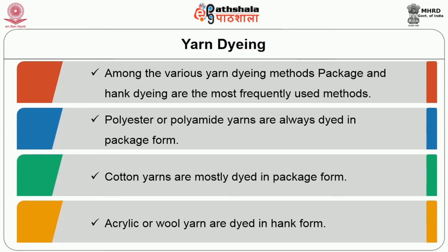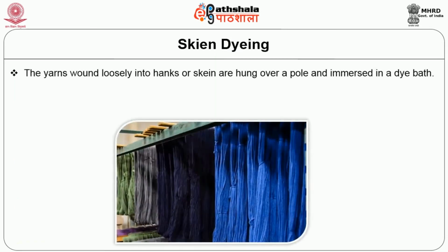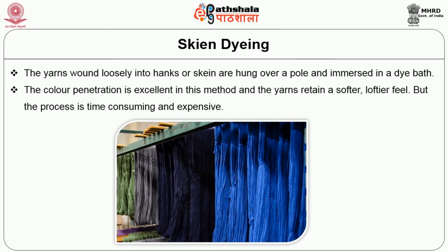Skein dyeing: the yarn is wound loosely into hanks or skeins, or hung over a pole, and immersed in a dye bath. The color penetration is excellent in this method, and the yarns retain a softer, loftier feel, but the process is time consuming and expensive.